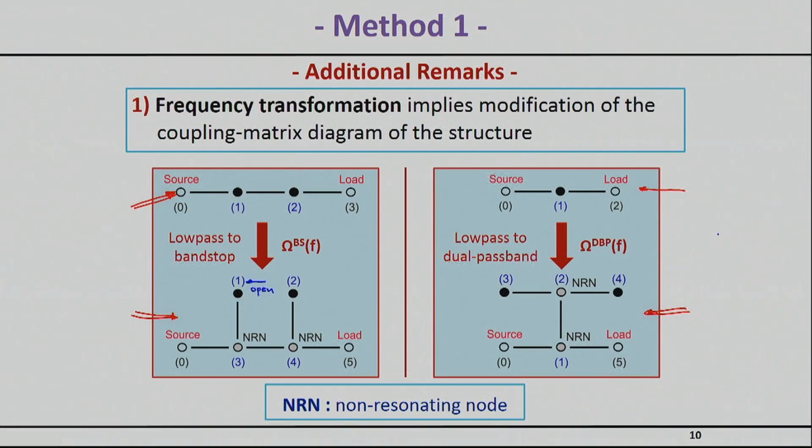You have this coupling section here that basically introduces a phase shift beta L of 90 degrees. Remember, we talked about inverters having a phase shift of plus or minus 90 degrees. So if you go back to the Smith chart and you bring that in your mind and you look at an open 90 degrees away, the Smith chart is 2 beta L, so that means you're going to transform this thing at 180 degrees. Guess what? You go from an open to a short. So that means that the signal right here will actually see a short.